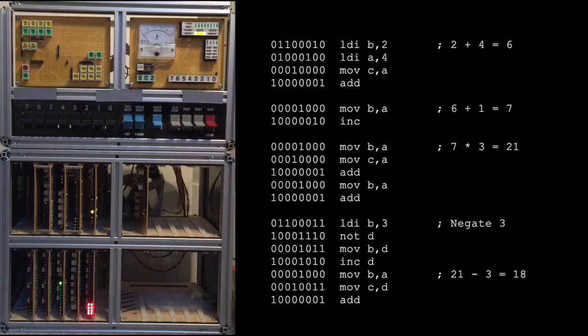Now, that'd soon get tedious, both for me and I probably suspect you as well. So I've knocked up a clock generator on a breadboard that's stuffed into the back of the upper enclosure. You might have noticed it earlier on in this video. This generates a nice square clock wave at a steady speed using a 555 timer chip along with the usual resistors and capacitors to set the clock speed and duty cycle. I've connected this direct to the clock line and power for the clock is routed through the run stop switch.